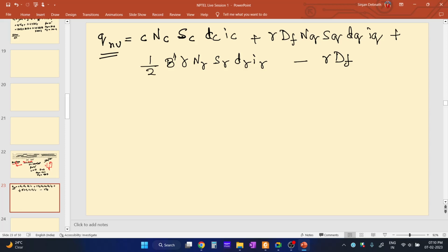So now for strip footing, this is a strip footing. So for strip footing, the shape factors SC, SQ, and S gamma, all these are 1. And since there is no inclination, that is, it is totally on the ground and there is no angle, IC, IQ, and I gamma are also 1, because there is no inclination, nothing, and the base is also horizontal.